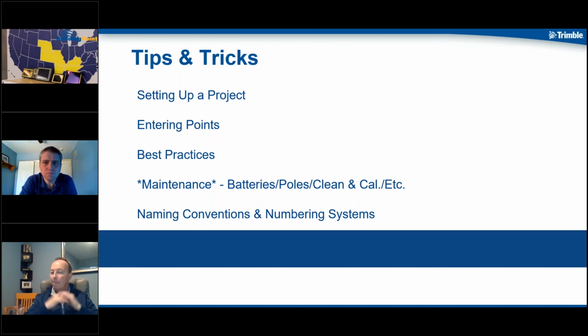Some of the other things, we want to make sure we take care of our prism poles. We want to make sure that we're checking and making sure that those are in good plumb. Those things do get out. We don't want to use that prism pole as a strong arm or something. We don't want to throw it in the back of your truck. We want to take care of that gear. We want to make sure that we've got our robotic total station. A lot of my customers, I stress that, and we stress that in our training, a lot of our customers put that thing in the child care seat, or they'll put that thing in the seat belt in the back of their truck. They don't arbitrarily throw it in the bed of their pickup and then let it bounce around. If you take care of this investment that you've got in front of you, it's going to take care of you. That's an old cliche, but it's true, okay?